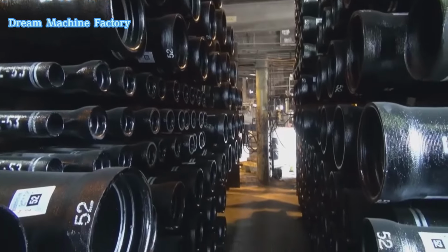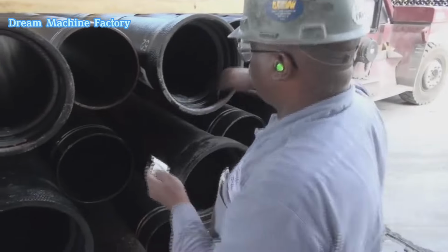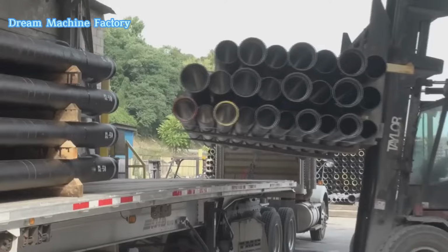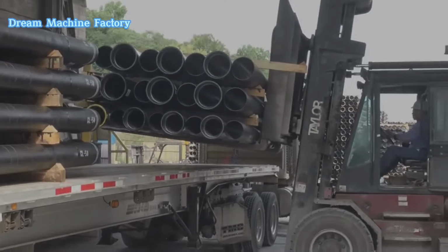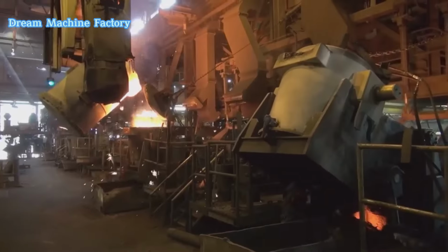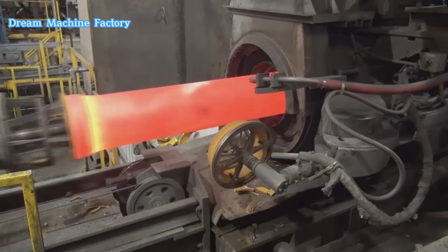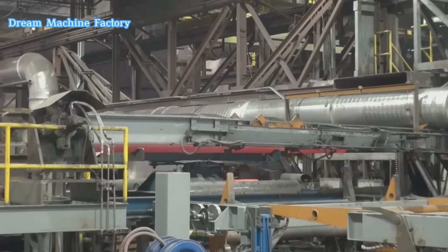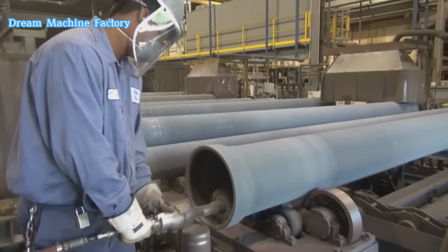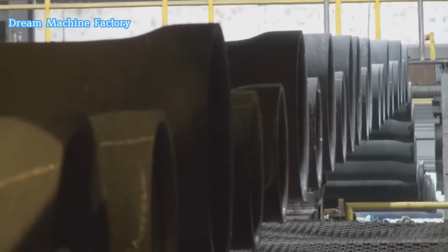Once the cement lining is applied, the pipe moves to the coating stage, where a thin asphaltic seal coat is sprayed onto both the interior and exterior surfaces. This coating helps retain moisture in the cement for proper curing, while also providing an additional layer of corrosion resistance. After coating, the pipes are bundled and left to cure for at least 24 hours to ensure proper adhesion and durability. A final visual inspection is conducted before the pipes are loaded for shipment, guaranteeing that only high-quality products reach customers.